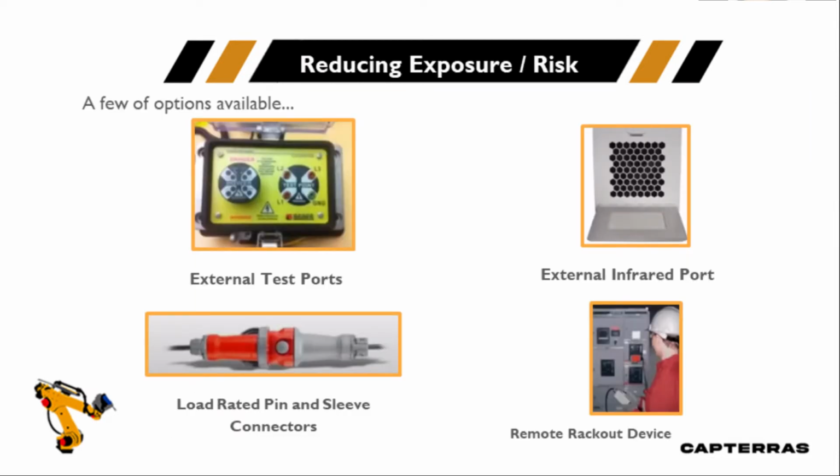The reducing exposure and risk. A few options available could be external test port. This device reduces the exposure and risk for test voltage. Then we have the load rated pin and sleeve connectors in case someone did disconnect it under load. Then the external infrared ports, and finally the remote lockout device.